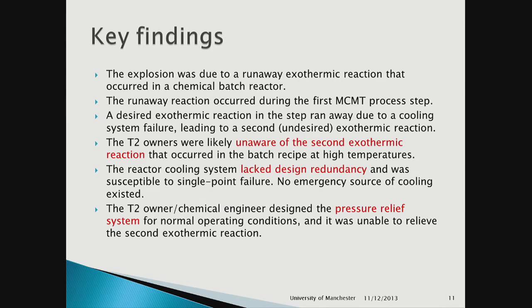The explosion was a runaway. There was a reaction, the red letters basically, that they were completely unaware of. The reactant cooling system had no redundancy in it. It was a single point of failure. If the mains wasn't on, it went bang. And they didn't legislate for that. The chief engineer designed the pressure release for the normal operating conditions, but was completely unaware of that 8 times more exothermic reaction. That was it.